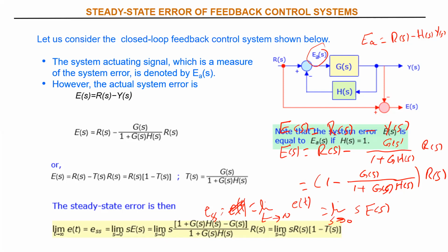You have a sensor, and you set the input as, say, 25, a certain degree, and then your controller will work such that we hope Y will be the same as R. If Y is different from what you set, from your set point, after a long time, then this signal will activate and give a command to the compressor to work again.